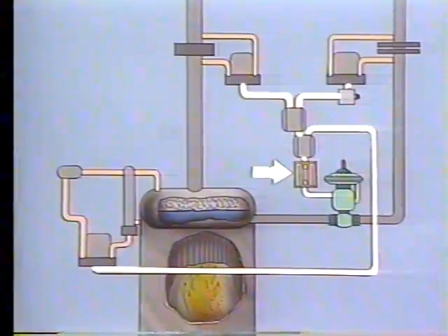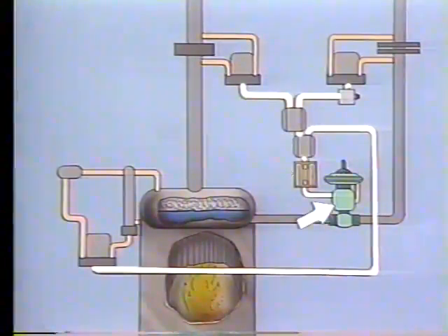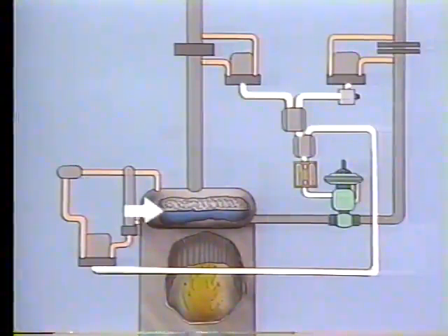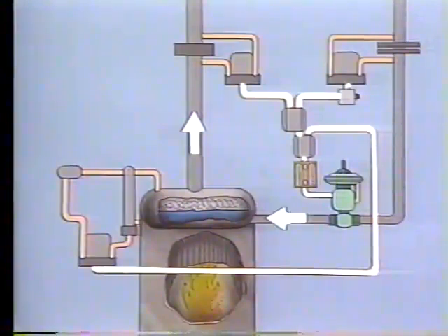After computing the difference between its input signals, the feedwater controller compares the difference against set point. It sends a corrective output signal through the hand auto transfer station and on to the final control element. The final control element repositions the feedwater flow control valve to regulate the feedwater to the boiler drum. This process continues until the drum level returns to set point and the steam flow out of the drum is balanced by the amount of feedwater into the drum.